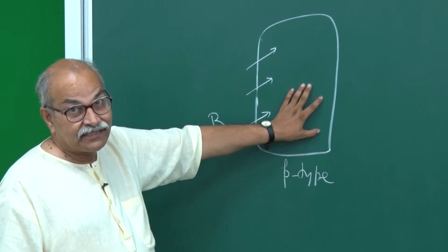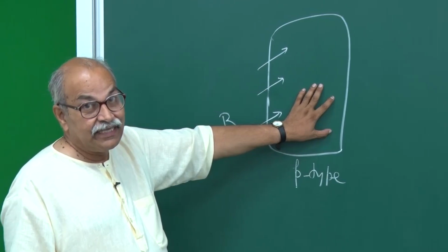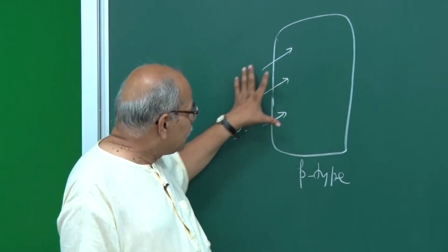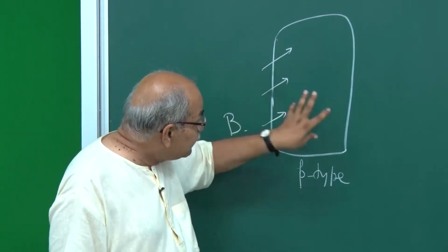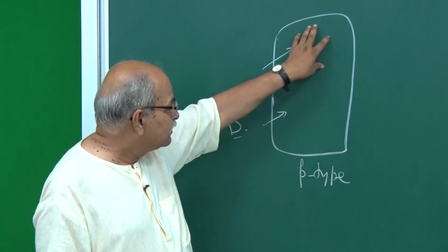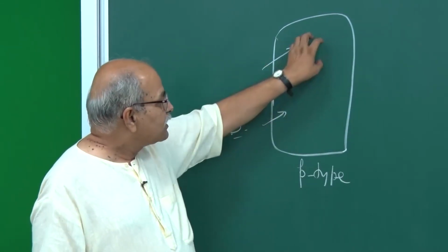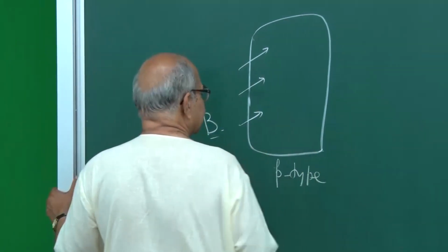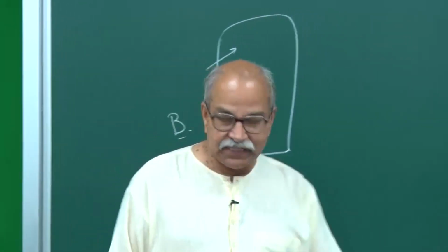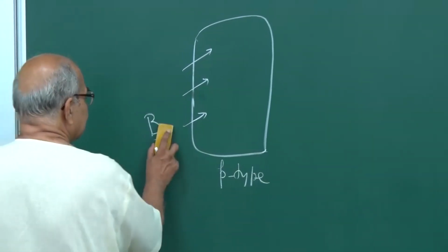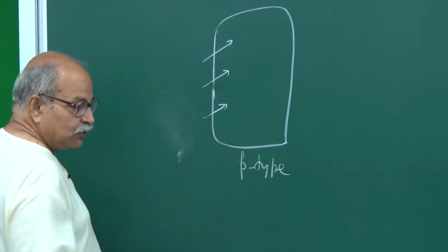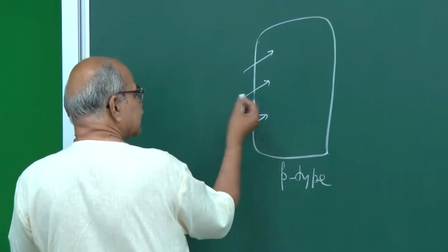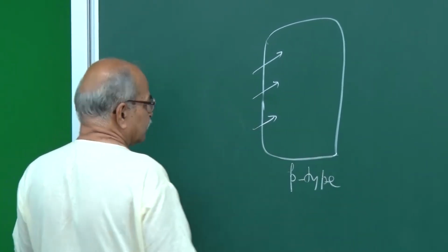Silicon I am taking as our model semiconductor. In any kind of semiconductor you have to do all this processing, and so through very controlled processes, without finally disturbing that crystal structure, you have to put these impurities at those lattice sites. So, this whole thing becomes p-type, and once this whole thing becomes p-type, after that you, in a very controlled fashion, diffuse n-type, and for that some pentavalent impurities like arsenic or antimony.